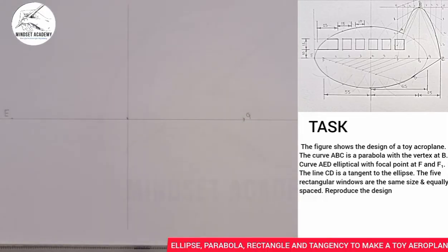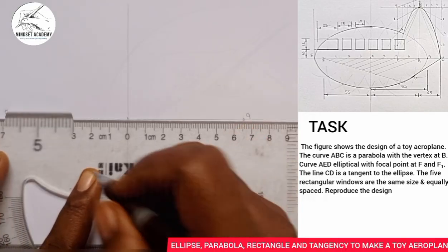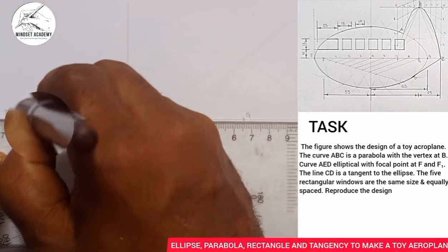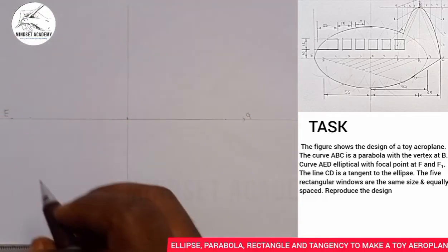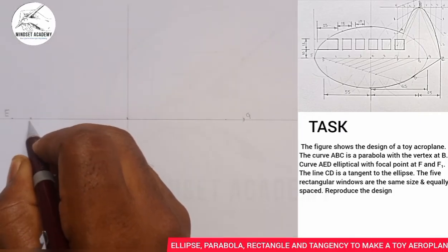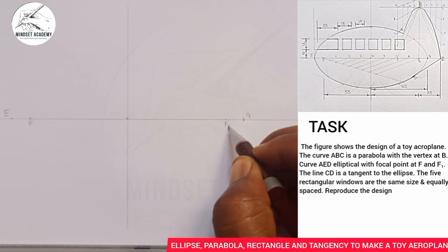Now, once I've done that, the next thing is we're told the focus. We have F and F1, so we're only given one of them, which is F. So from this center here to the focus, we are going to have 55, right? So I'll measure from this point to F. From 0 to F is 55. Also meaning that from 0 to F1 is also 55. So that will be my F and F1 respectively.